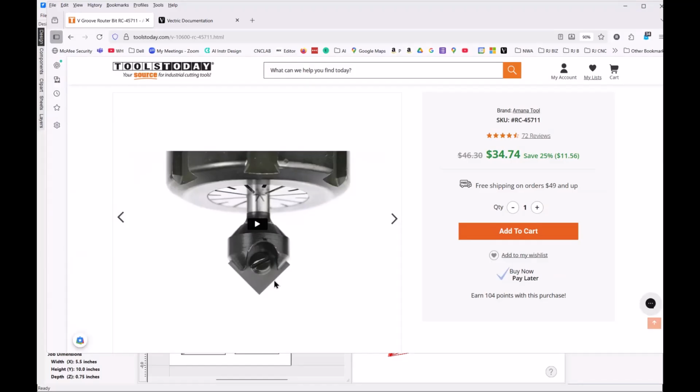The only caveat I have on this is that when I've changed these, sometimes rotating the insert can be a little tricky to get precisely centered again. I have about 6 of these that I rotate between when I do my classes, and a couple of them are a little hard to set. I had one today that I just tested on. I rotated the angle and it came out perfect. Others I have to tweak a little bit. We'll take a look more at fine tuning some of these in the future.